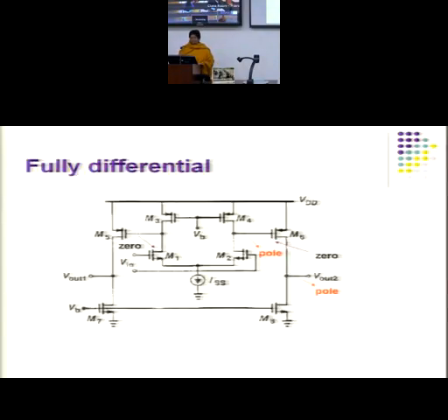Okay, main signal path is from Vout to this intermediate node to Vout. It's a signal path. So anything that is coming within the signal path directly or indirectly is going to introduce a pole and a zero. Okay. So look at the structure of this cascade. It is actually a fully differential pair followed by common source amplifier.